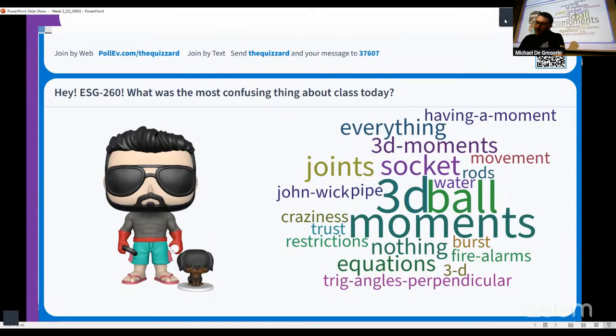And so if you're trying to build an intuition on 3D moments, I would very much encourage you to draw these free body diagrams as planar 2-dimensional diagrams and see how the moment behaves in each of those planes. Because that will give you a better sense of how it rotates, right? I think 2-dimensional is much more intuitive when we look at it, right?